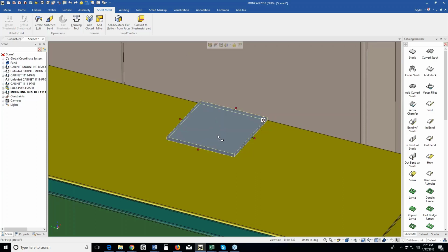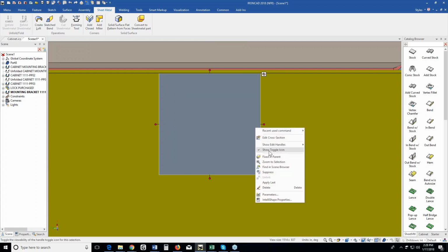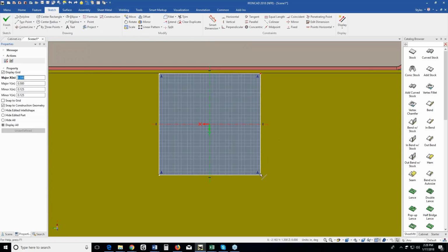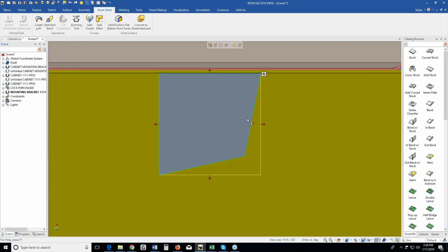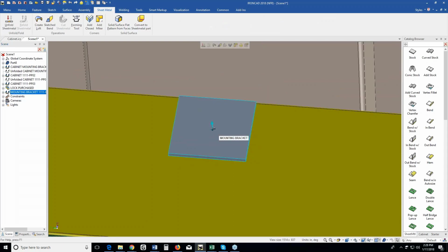But what I want to show you about the size box handles is that these are basically the handles for the bounding box. So just real quick, if I was to change the geometry on that, what you would see is the outline for the overall bounding box of the sheet metal part, okay? In this case, we won't need to do any of that.